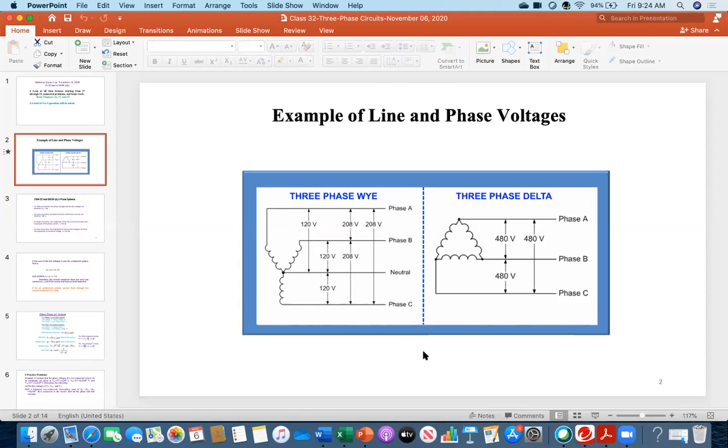For example, your home has a grounding system, or your company has a grounding system, or a building has a grounding system. For some reason, the system is unbalanced and some current is flowing through the neutral. So therefore, the problem is that this neutral line has some capability, because if current flows through the neutral, then this coil will be heated up. And if the current is too much, and if current flows for a long time, then this neutral can be burnt out, disconnected, or damaged.